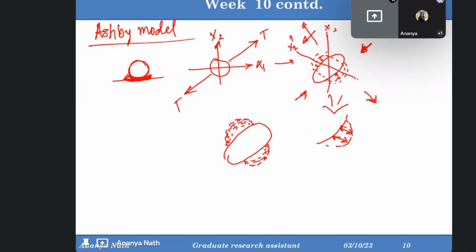So by punching out the dislocations, you can get the spherical shape again, because whenever you try to push it in this direction or pull it in this direction, these dislocations will try to restrict the motion and will not let the particle regain its original shape and size. This is why punching out the dislocations is important.